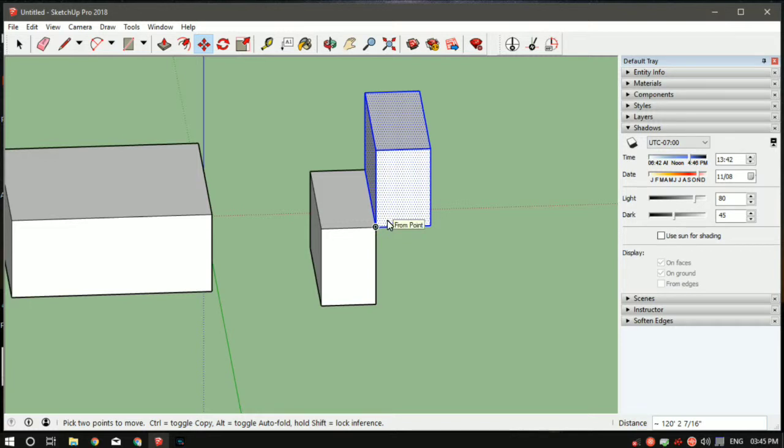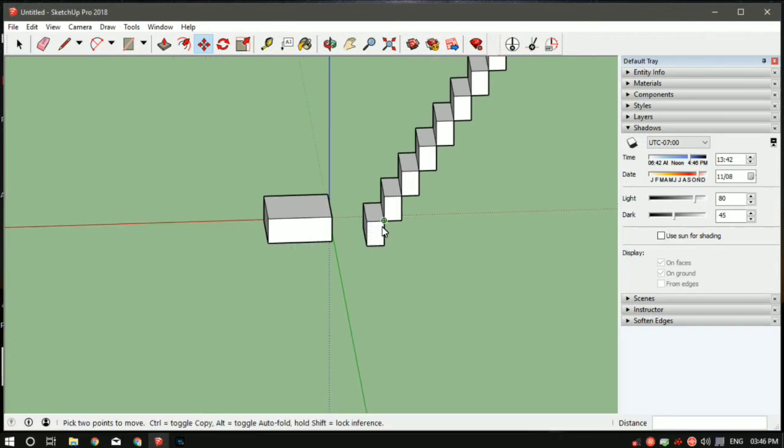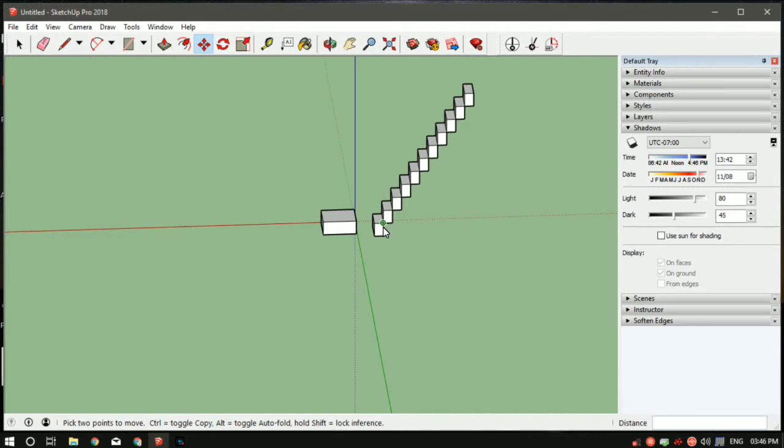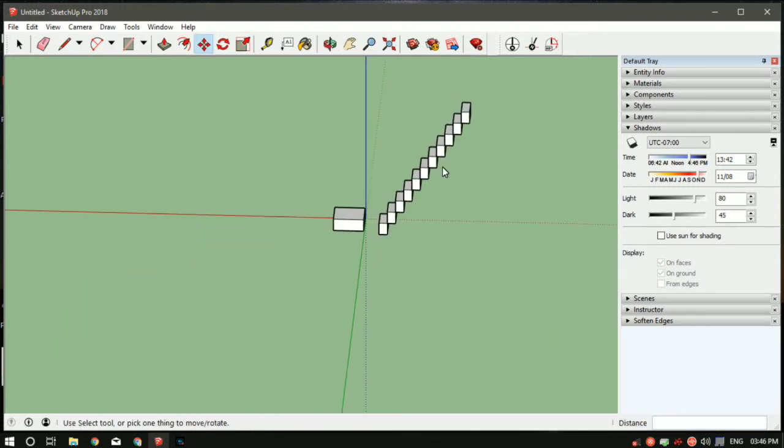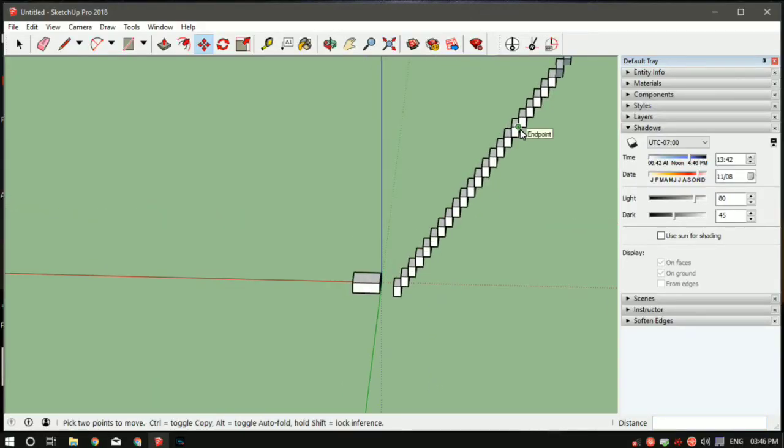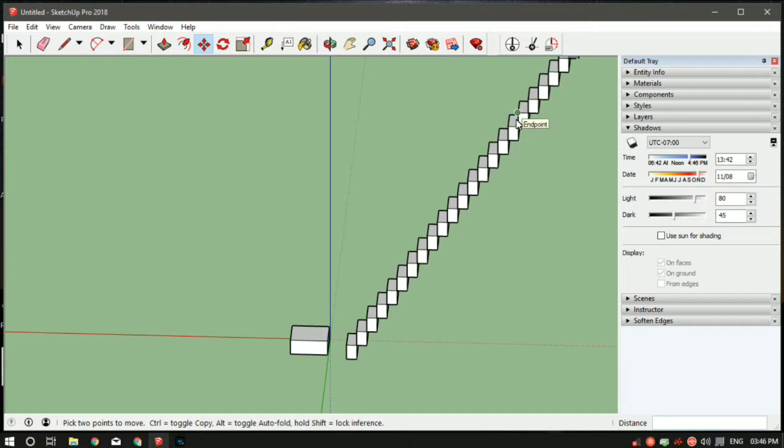And then what you've got to do is, let's say you want to follow this pattern 10 times. So type the X key and then press 10, and then press enter. So now the entire cuboid is being copied 10 times, as you can see from here. Let's say I want to copy 100 times. Again, press X, 100, press enter. So now it's copied 100 times, you can see. Let me just select the entire thing and delete it.